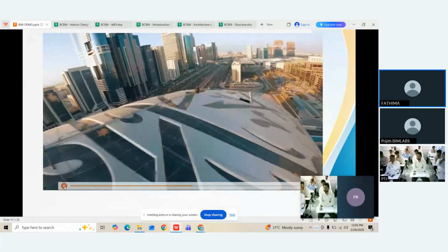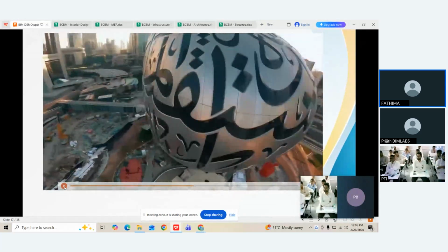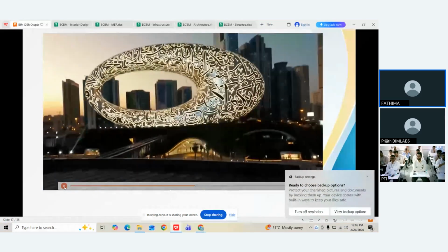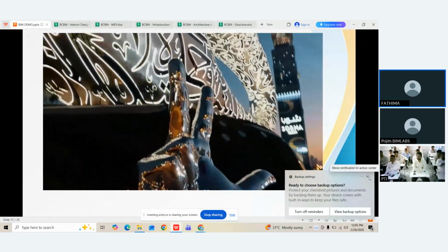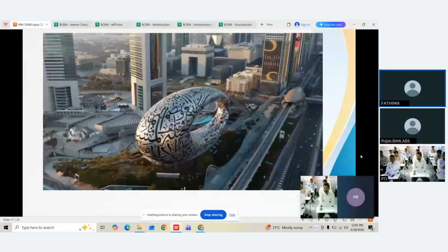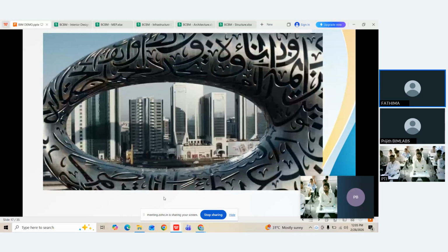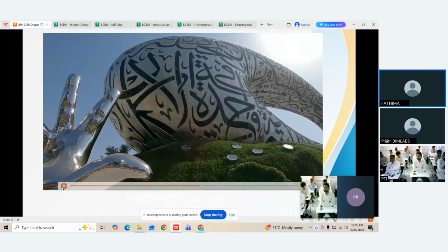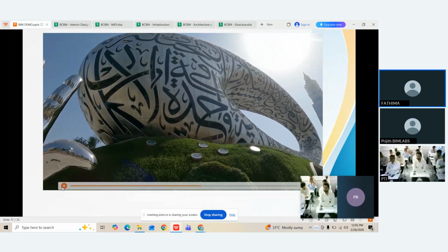The small construction crew conceals the intricate engineering required to create each panel. No two fiberglass panels are alike due to the building's shape and calligraphy cutouts. Before the stainless steel finish and glazing, each of the 1,024 panels must be separately molded and fabricated. It's a labor-intensive procedure that allows just 6 panels to be made every day.